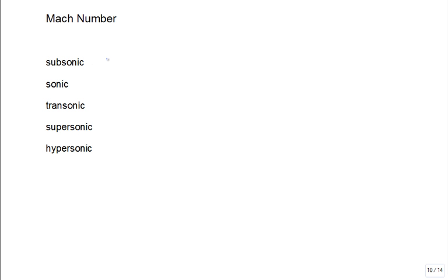Subsonic, the Mach number much below 1. Typically, if you're below 0.3, a lot of times they'll even say the compressible effects of gases are negligible. But be careful. You can have something where it's not flowing fast, but you've compressed it, and it's very compressible.